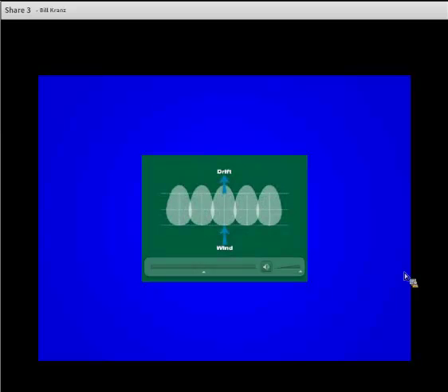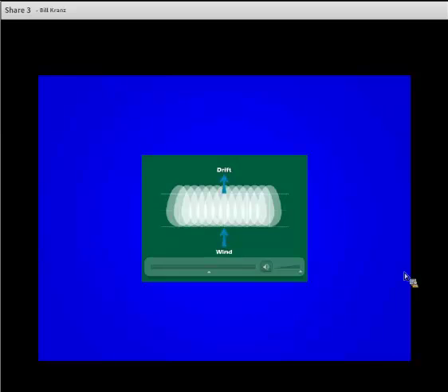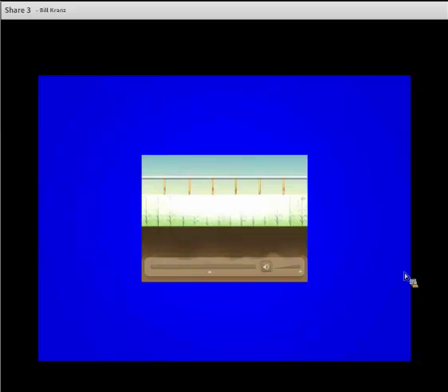So in here we're looking at the high pressure impact and the effect of spacing between the sprinklers, and we really need to try not to cut corners on this. We have wind out there, which blows on a daily basis. We're going to get some distortion of the water patterns here, and so the idea is that we put these sprinklers on the system close enough together so that the wind drift effect is not as significant, and that the overall infiltration of water into the profile is relatively uniform.